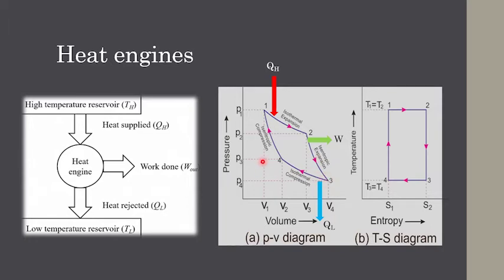Now, since all of these steps are reversible, we can also refer to them as isentropic expansion and isentropic compression. It is in the isentropic expansion step that we generate the useful work. In some variations of the cycle, there is also work input during the isentropic compression, but we will deal with that in our future lessons. For now, the only work involved is the one coming from the isentropic expansion.